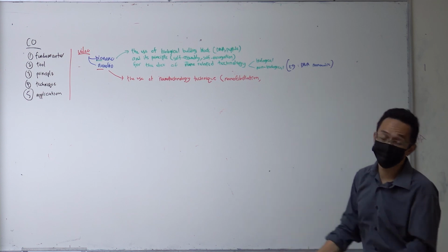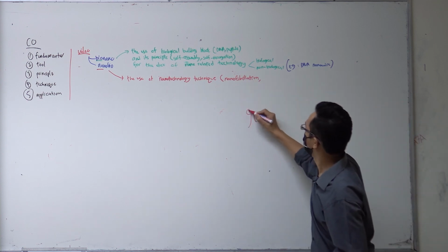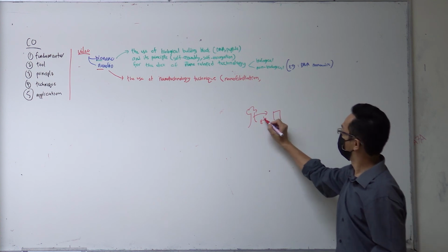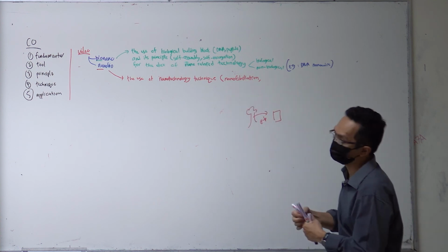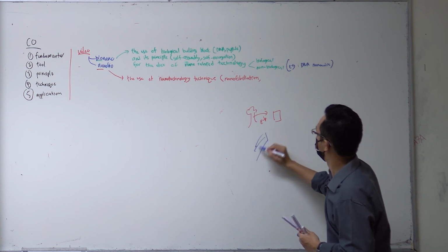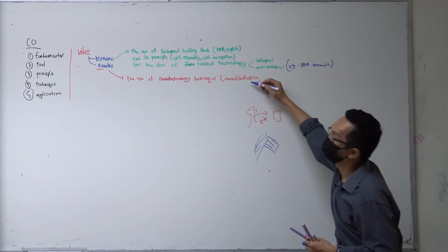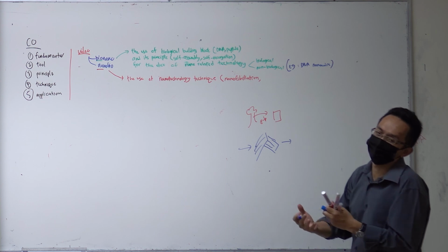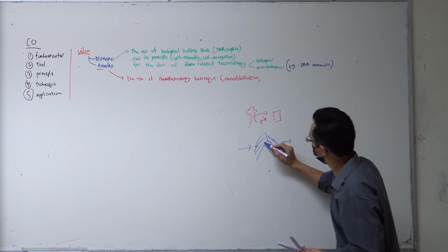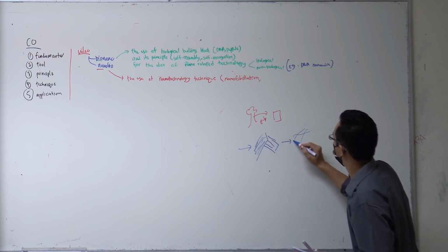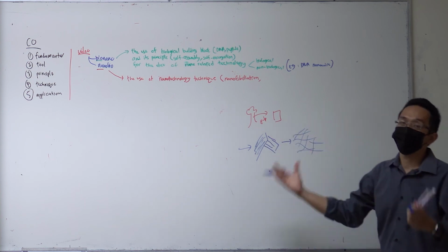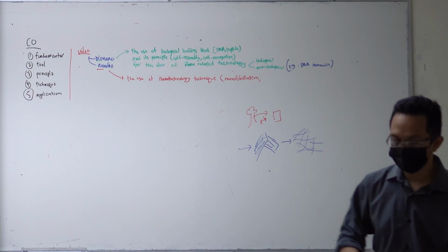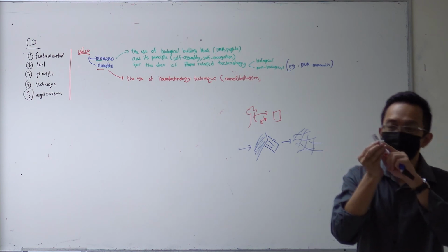It's like you have the tree, and then you want to make a paper, right? In order to make a paper, you use a pulp. Okay, so nanofibrillation is that the pulp is something like this, they have fiber like that. That's the pulp. So nanofibrillation is basically you subject this pulp to a high-speed homogenizer or crusher, so that this fiber inside the pulp will become fibrillated, will become free. Because the pulp itself, if you look here on the paper, if you try to take this thing, you will see a strand of fiber.